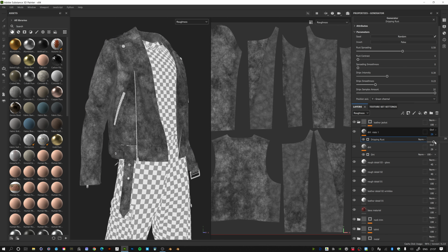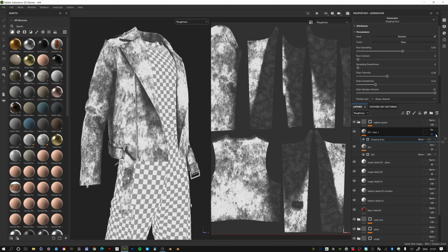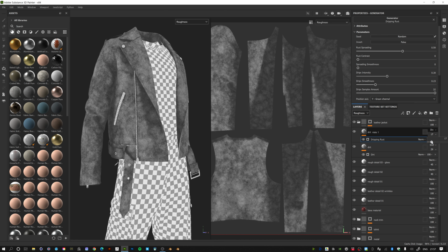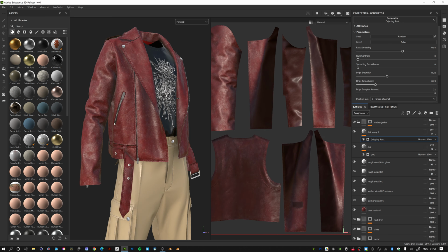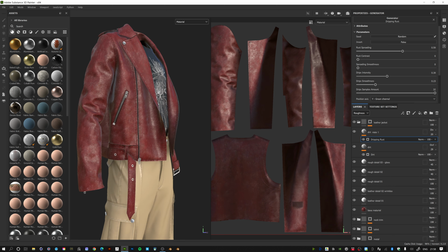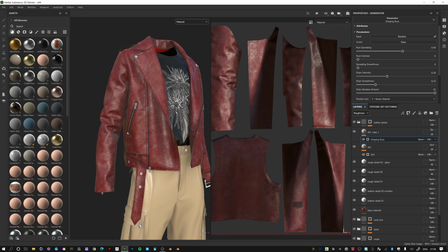And right now it's set to overlay, and I can bring this back up using, again, opening this menu and trying a different blending option. I'm going to look at divide, and then I'm going to reduce the intensity on this divide blend to about 20%, and then look back at the material of this, and now we have some kind of dirt coloration added to this, a little bit of roughness added to this as well.